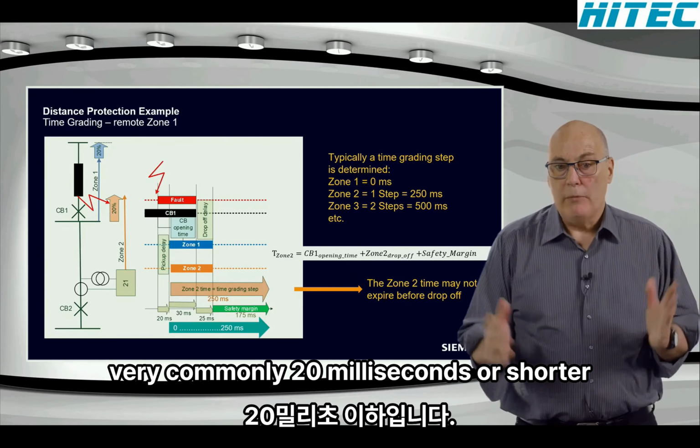That's where the zone 2 then comes in. The zone 2 will then clear it here. When the time delay expires, it will trip as a so-called remote backup functionality. That is something one must remember. It's not the primary purpose of zone 2; it is a secondary purpose. In this remote backup functionality, it can be that the remote backup must be graded with a local backup.